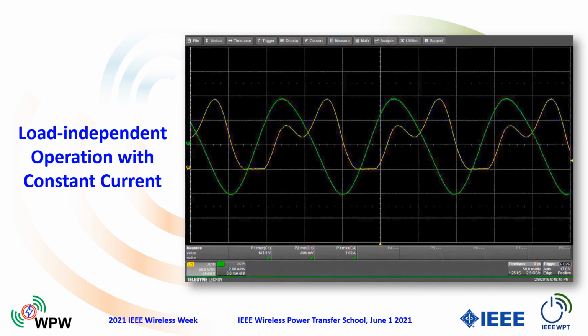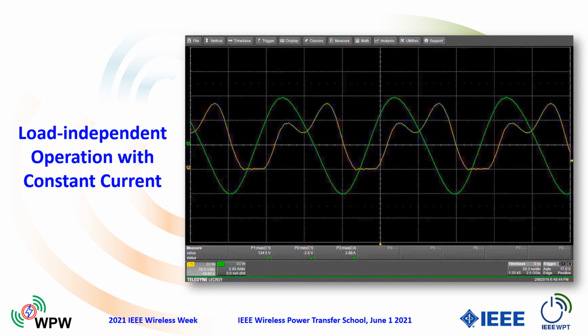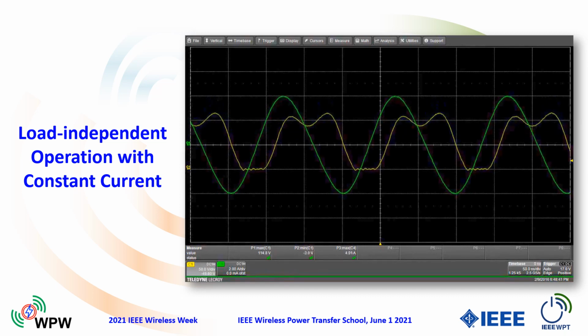This is just recorded off the oscilloscope as I have a receiver that I bring up and move away from a wireless power transfer system. And you can see the yellow there is the voltage equivalent resistor, always maintaining nice 0 volt. I also, with this circuit, can achieve constant primary side current, which is very useful because I then have a constant magnetic field generated.